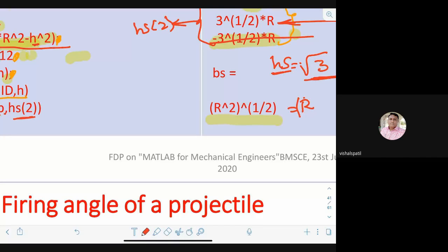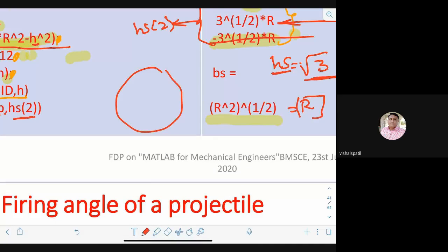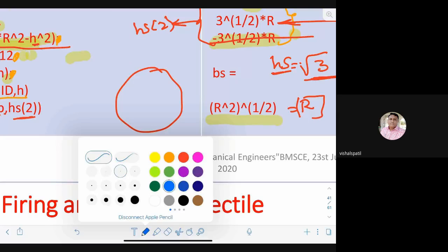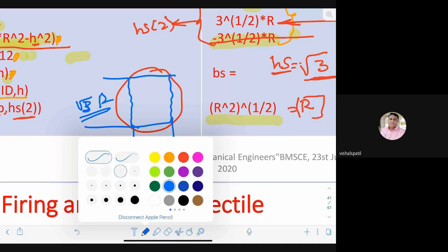So the optimum value that you are going to get from this log of wood is a rectangle whose width is equal to radius and whose depth is equal to root 3 times radius. This will be the optimum value that you need to look at.